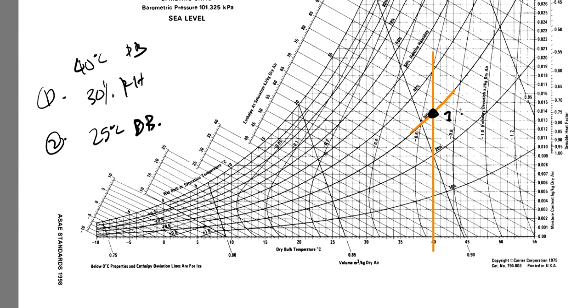Okay, and it's cooled down to 25 degrees C, which is somewhere here. Since this is a sensible cooling process, the humidity or the moisture content is constant, maybe right here.